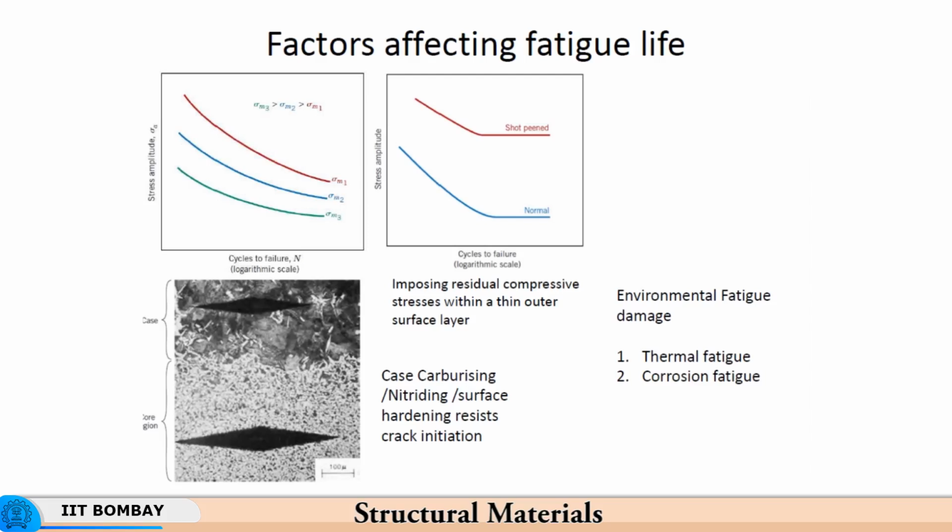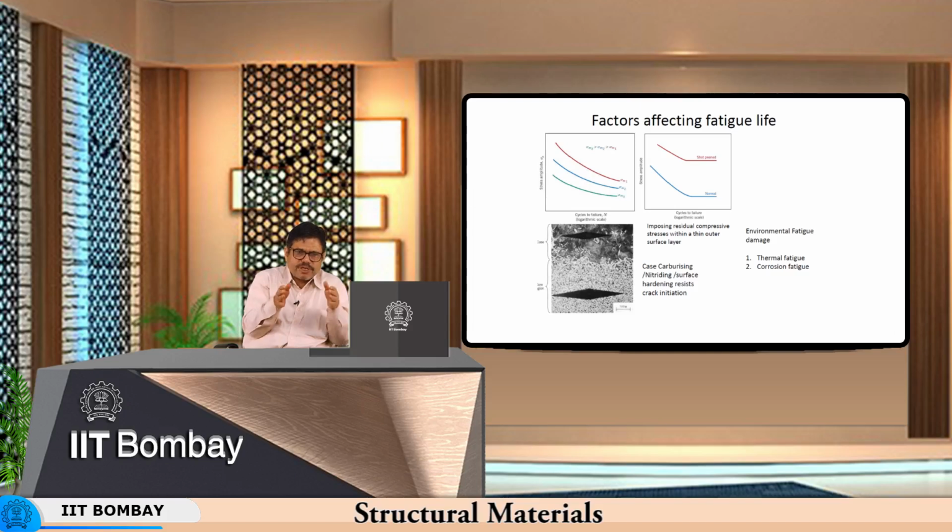Naturally, what happens is that compressive stresses are created on the surface, because the material tries to pull the surface back to its original surface area, but the material refuses to come back. Therefore, these are so-called unreleased elastic stresses which remain behind. These unreleased elastic stresses are compressive in nature. So, you have a shot-peened surface which has a compressive residual stress present.